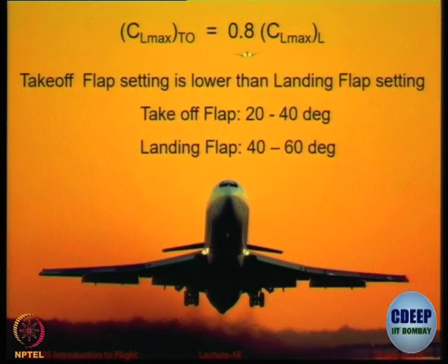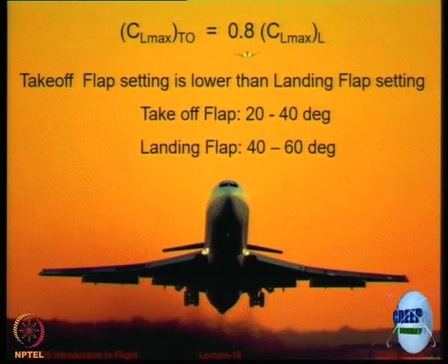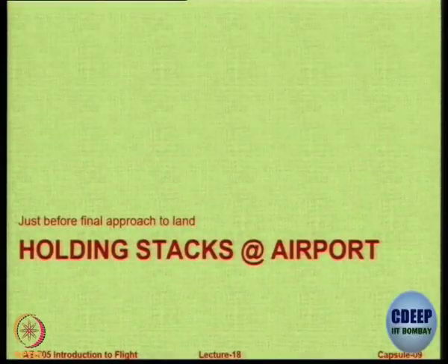So therefore the flap setting that is used for takeoff and landing generally varies between 20 to 40 degrees for takeoff and 40 to 60 degrees or even higher, 65 degrees also is common for landing. Okay. So that is the beauty.